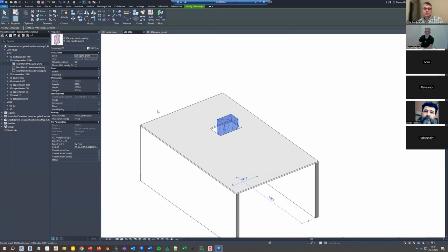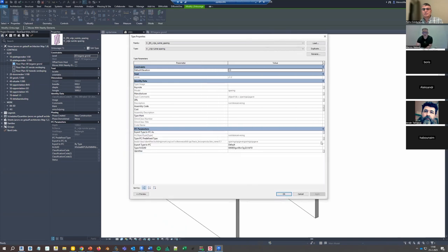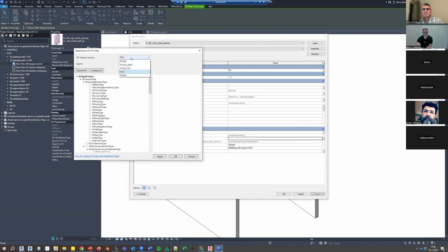And what you'll see, and this is why there's a big difference between what IFC version you use. In 4x3, it's called an IFC virtual element. In IFC 4, it was still a generic model, so basically an IFC building element proxy. But the way this is supposed to export, I'm not sure if this is the answer, but it's still nice to see if there is no virtual element here.